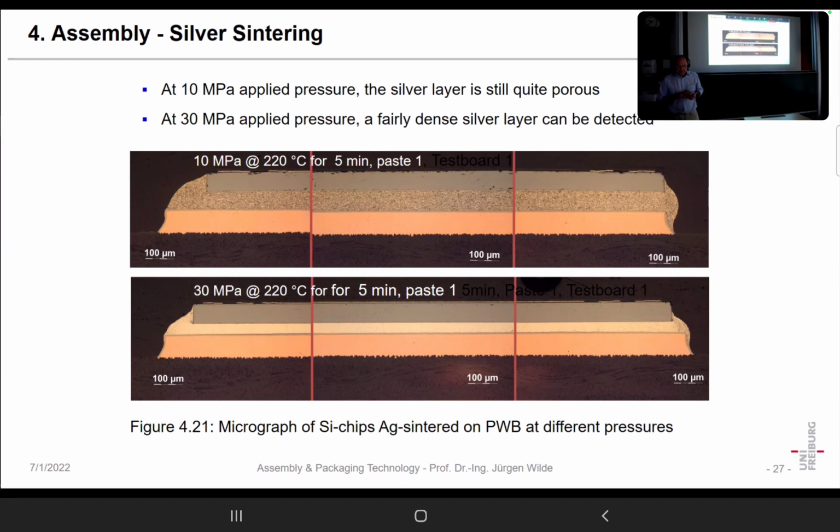The power electronics people had several developments. One of the developments I have shown you is direct bonded copper, that means direct copper bonded ceramic substrates, which have a high thermal conductivity. The copper distributes the heat very well. We can solder against it. Electrical conductivity is very good. All is fine. But there was one disadvantage when we want it to live for very many cycles.